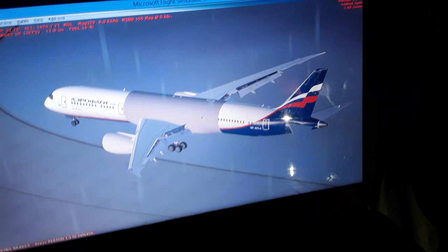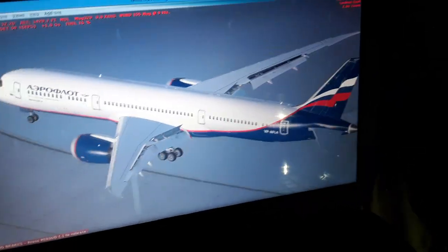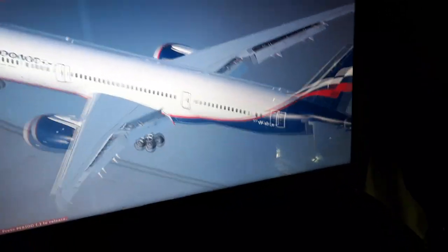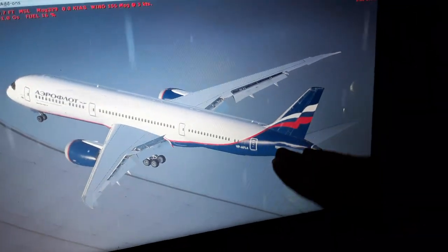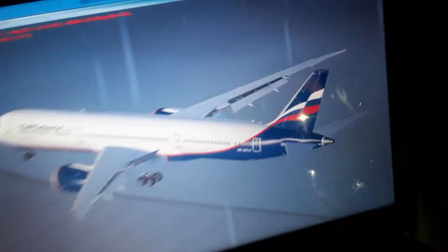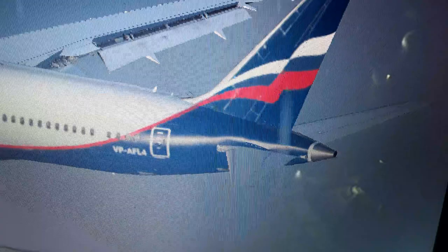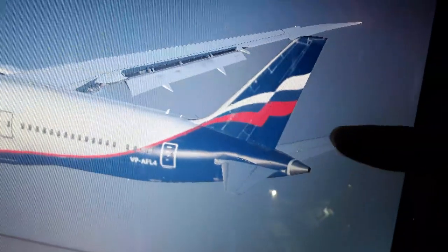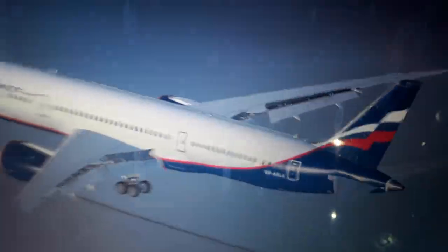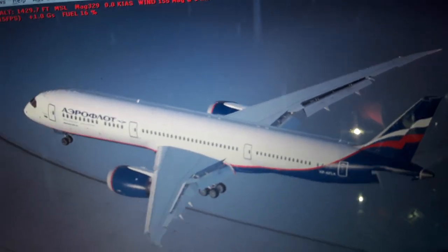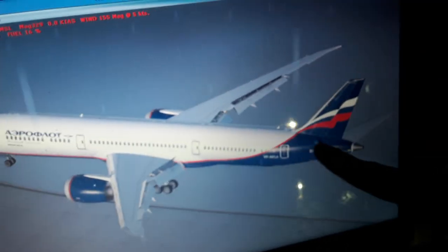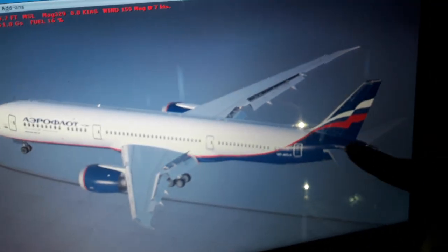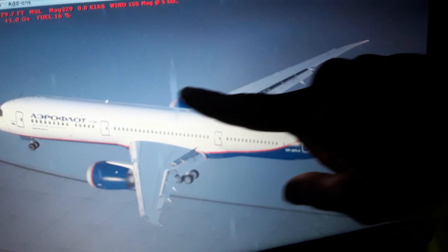So this is the exterior view of the aircraft. As you can see, the horizontal tail stabilizer is this plan form, so we can trim up or down, moving up and down the whole surface area of both left and right horizontal tail. And we have also the vertical tail, we can trim also that in flight. So you can see here is the longitudinal axis that transverses the horizontal tail. We have the thrust vectors from the engines.